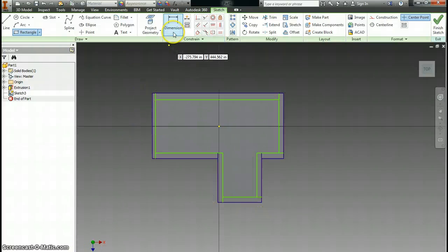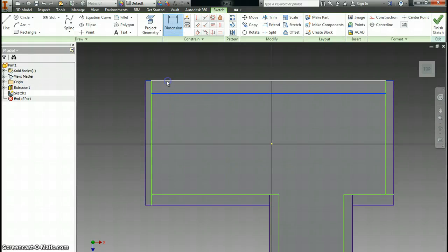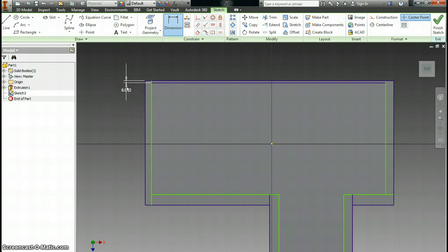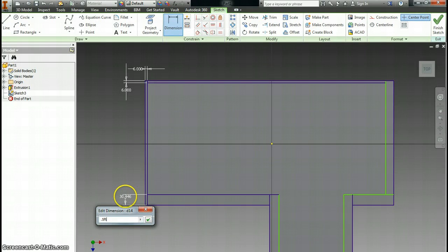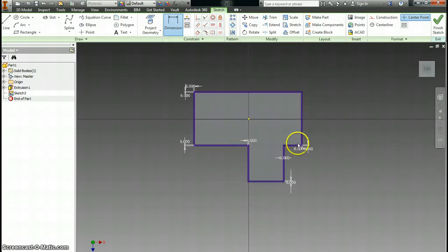Alright, so now I've put walls on. Now all my walls need to have uniform thickness also. Now exterior walls tend to be thicker because they have a larger, a 2x6 piece of wood in between them. Interior walls tend to be thinner, but for the sake of math, let's just make all of our walls 6 inches thick. Or you could put in half a foot. So you could either put in 6 inches like I'm doing, or you could say 0.5 feet, and they're going to be the same.